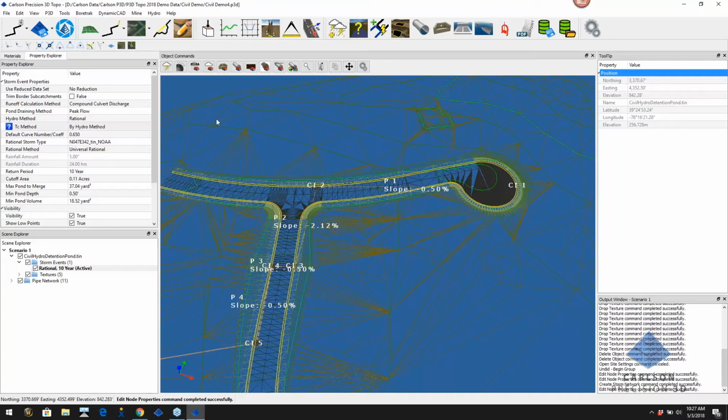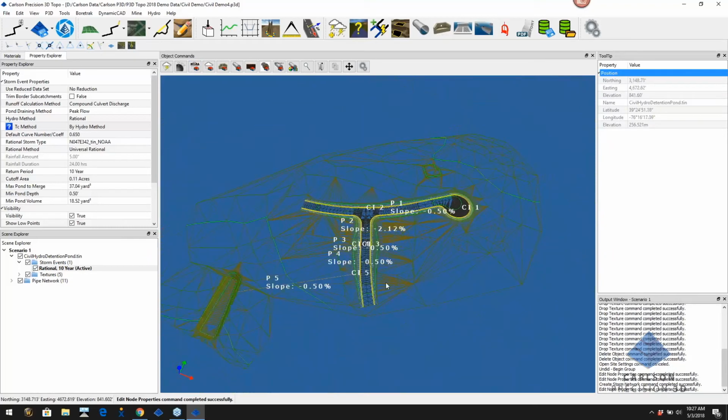You can still do that here. You're not restricted, but it sure is convenient to click that button, and because we're tied to grid, we get the rainfall data. So, to me, in North Carolina, as long as I can justify where my stuff comes from, whether it's Denr, NOAA, the city of Raleigh, whoever, they give me those options. So we've got that here for you.